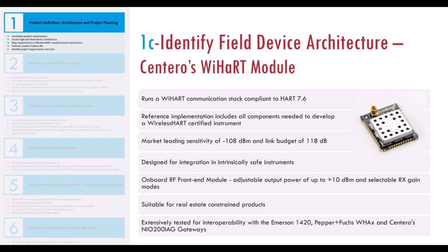It is designed specifically for inclusion in intrinsically safe instruments. It does have an onboard adjustable RF front-end module, which allows you to adjust the power up to 10 dBm, and also a selectable RX gain mode. It is very small, suitable for inclusion in real estate constrained products, and it has been tested for interoperability with various different gateways and infrastructure devices provided by other vendors.